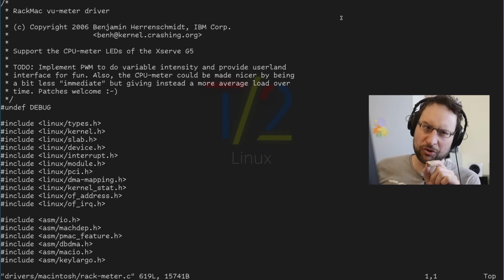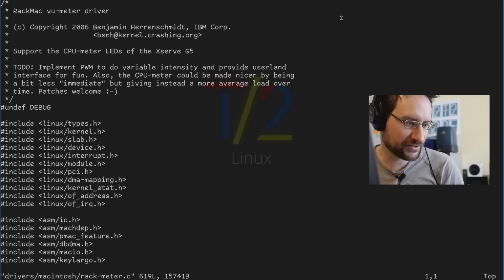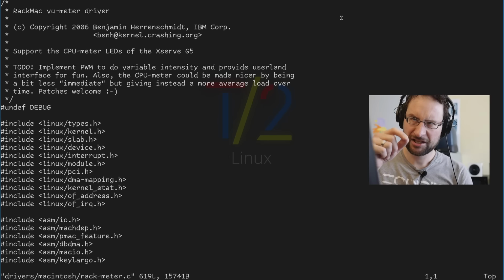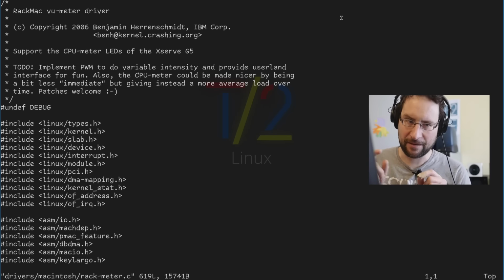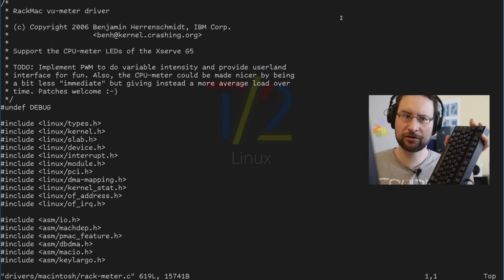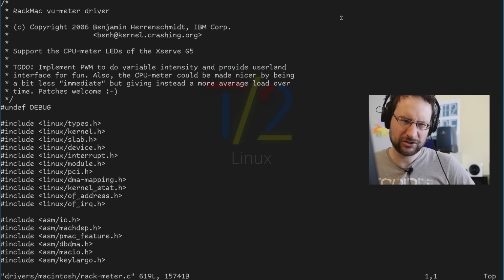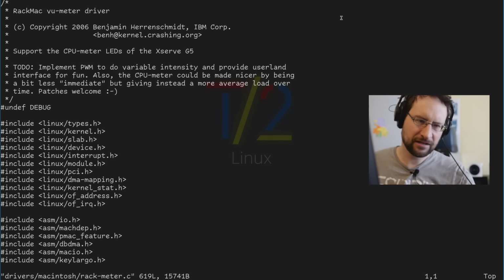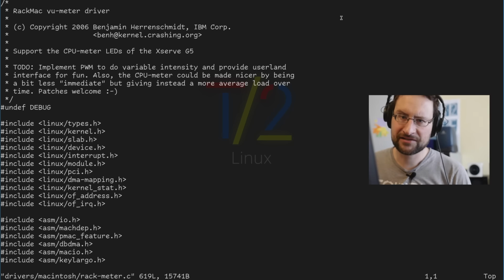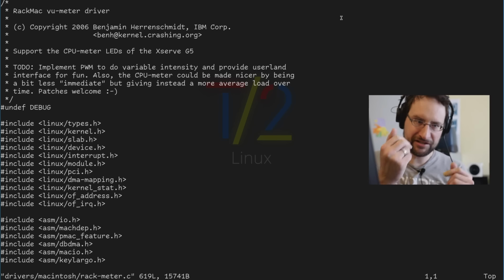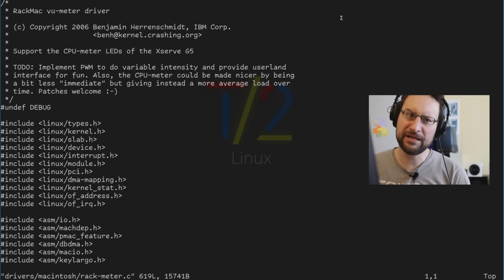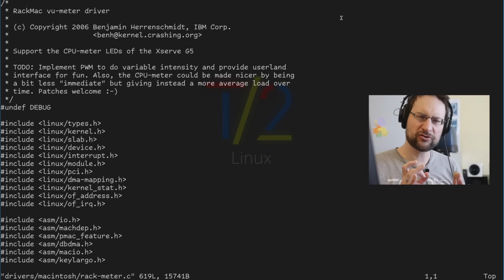In my opinion, if I were Linus Torvalds, there should be a generic Linux kernel load trigger, because we have LED triggers, right? Like caps lock, scroll lock, heartbeat, meaning your system is alive. That's what you have on embedded stuff, right? These triggers you can select in the Linux kernel LED class subsystem for your LEDs, or like I/O load or network trigger. And there should have been a system load trigger, but there isn't, because there's also other hardware.